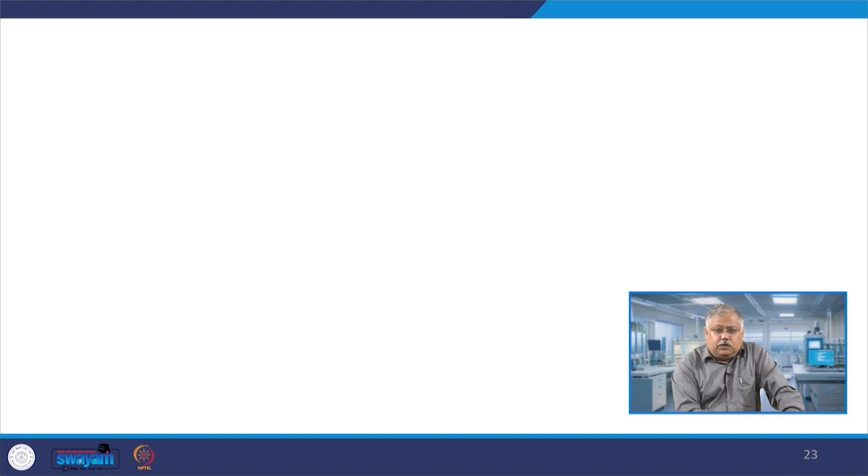So, with this we come to the end of this lecture series, lecture 1 on negative capacitance. We have learned what an LK formulation is. We have also learned how traps influence the negative capacitance, what the various coefficients, Landau's coefficients alpha, beta, gamma, are, and how they are related and how their values change with respect to that of the threshold voltage.